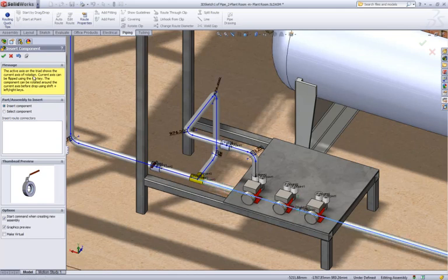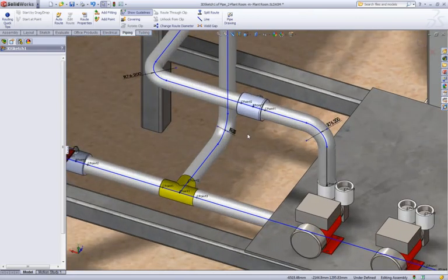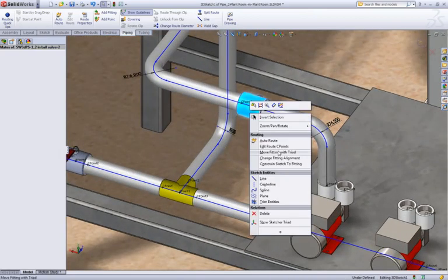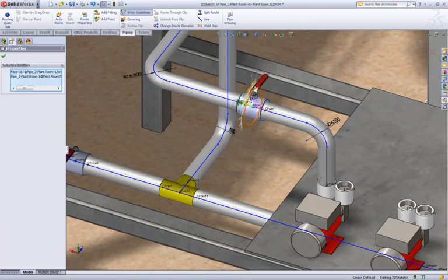The orientation of a fitting can be set when the fitting is placed, but if you need to move them later, you can use the new Move Fitting with Triad command. This brings up the familiar triad and allows you to rotate it easily using the on-screen ruler to snap to.